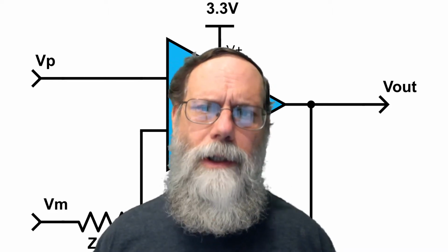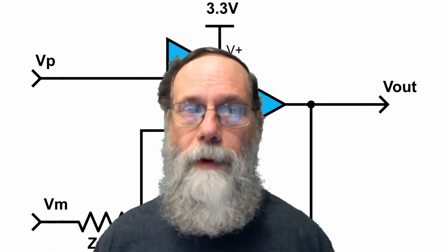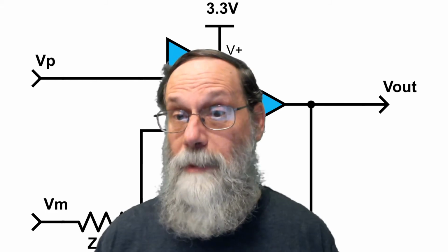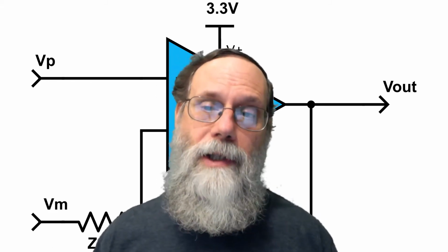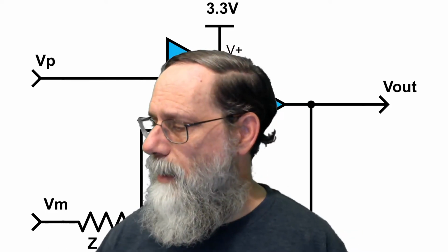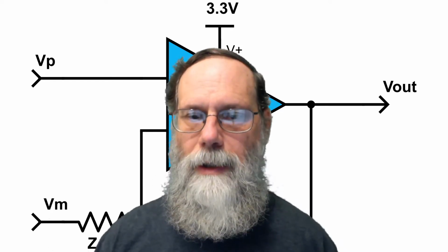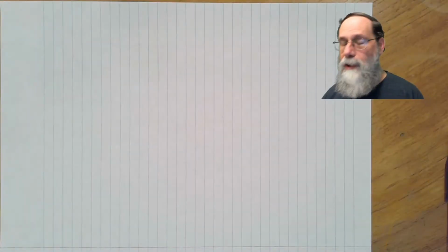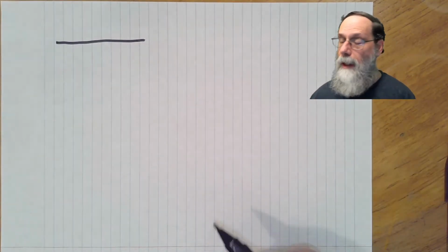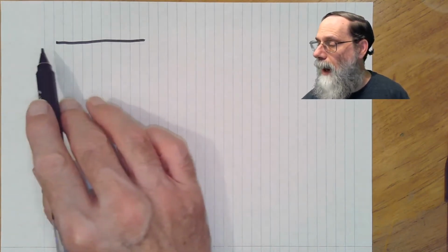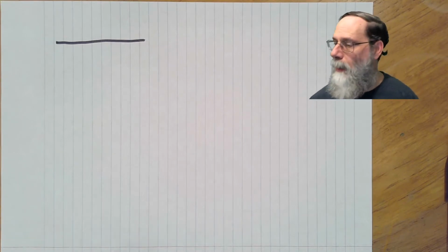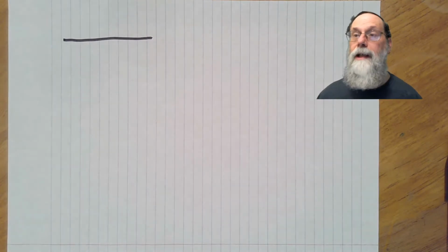And the only thing that we really need to be constantly aware of is that a voltage is always a difference between two, here they said points in space for physics, we'll actually be looking at differences between two nodes. What is a node? Well, a node is a mathematical abstraction of a wire, and we'll draw it on a schematic diagram as just a line. And what we're going to say is that every point on this line has the same potential. It's the same level in the field, so the voltage difference between any 2 points on the line is 0.